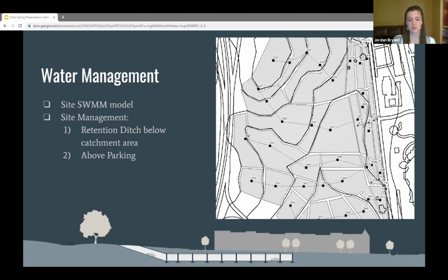There's over 27 feet of elevation change. In order to control the flow of runoff, we are excavating the slope ditch along Harewood Road. This was in the original plans for campus, and we found it was the most effective method in preventing the road from flooding. On the green above the garage, there are drains along the sidewalks to divert water around the underground structure to prevent pooling over top of it.